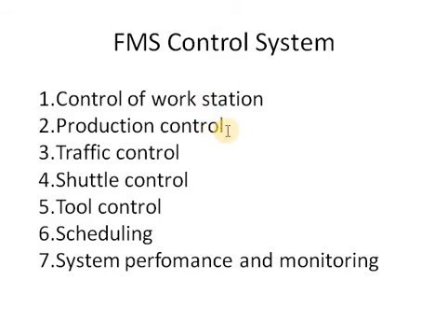If you're talking about production control, it includes the real-time control of the workstations, load-unload stations, pallets, desired production rates per day for the various parts, volume of raw material available, and tools and material handling units. A data entry unit is located in the load or unload area for communication between the operator and the computer.